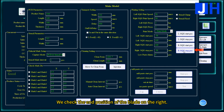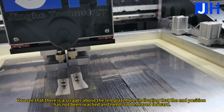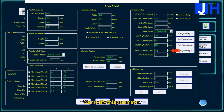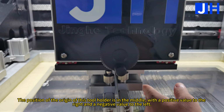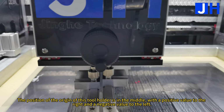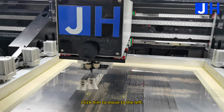We check the end position of the blade on the right. You see that there is a scraper above the template hole, indicating that the end position has not been reached and needs to be moved forward. We modify this parameter. We set the negative value larger, allowing the blade to move forward. The position of the origin of this tool holder is in the middle, with a positive value to the right and a negative value to the left. So we set the negative value higher and make it move to the left. Click it to move to the left.